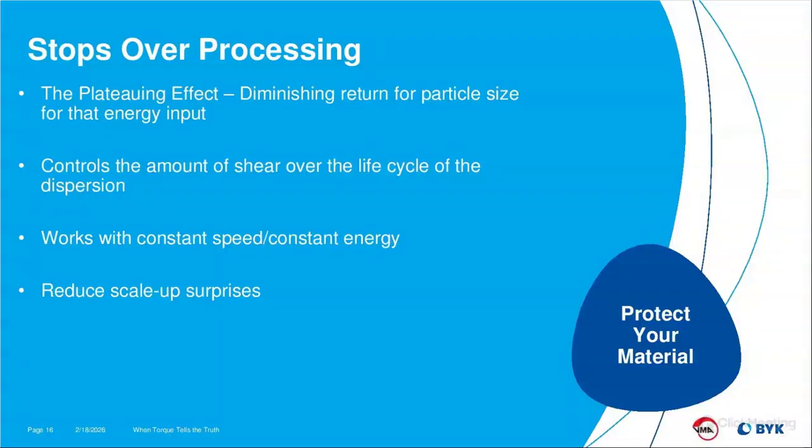Processing mentioned earlier, the plateauing effect, the diminishing return. We want to make sure that we're not exceeding the limits of our particle sizes or the material. We can control the amount of shear over the lifetime of the entire dispersion process, from the wetting to the deagglomeration all the way through. We work with constant speed and constant energy with regard to our machines and functionality.